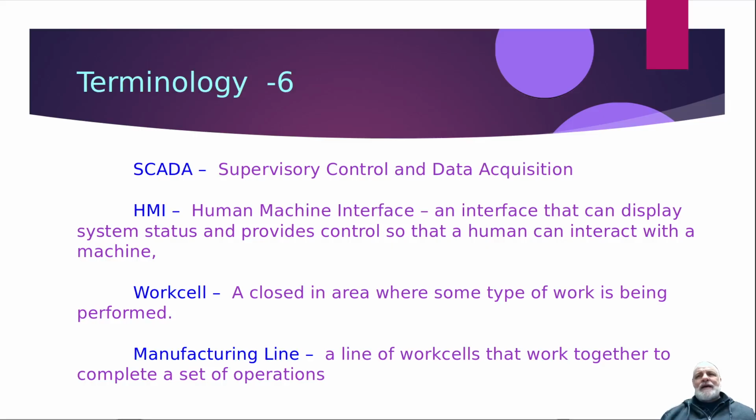Anything human related doesn't necessarily have to be real time, because for us to decide to go over and press a button to start or stop it, there's going to be delays in that. You want that to be controlled by a real-time computer that's going to stop it as soon as that sensor has been triggered.